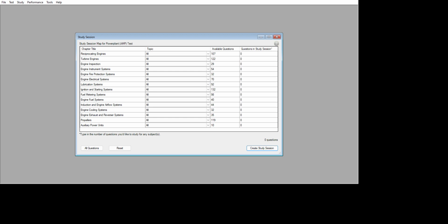What factor is not used in the operation of the aircraft gas turbine engine fuel control unit? Mixture control position. Because it's a turbine engine, you don't use mixture control. What action takes place when the cockpit control lever for a hydromatic constant speed propeller is activated? Compression of the speeder spring is changed.